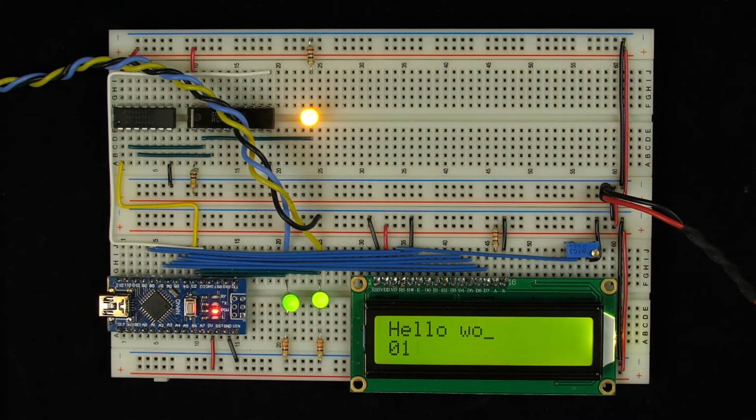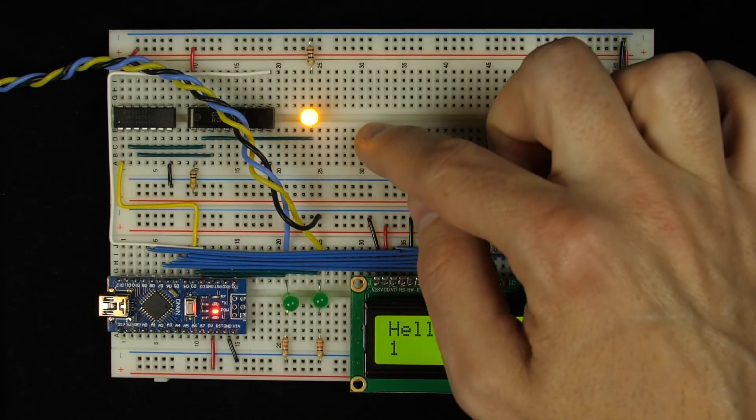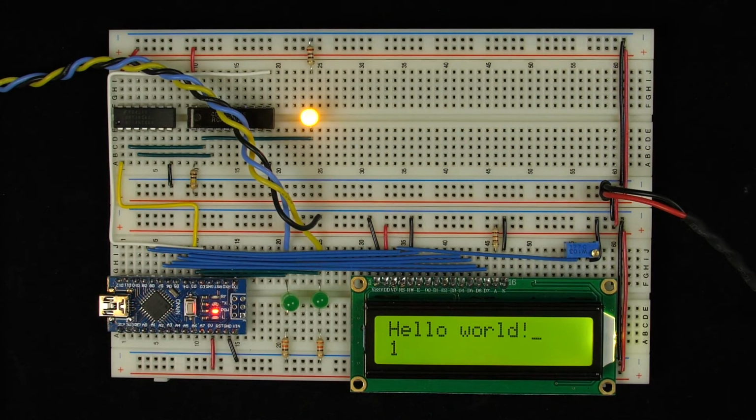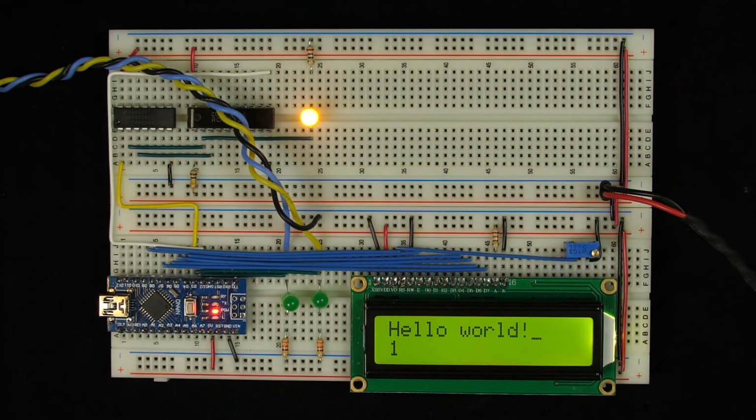So let's take a look at the receiver again as we receive a message. Now again, we've got this message where we received hello world without a comma. So was that a mistake or not? Well, because this LED is on, we know we received an odd number of 1s. But now we also know that our transmitter has even parity. So counting the parity bit, the transmitter will always transmit an even number of 1s. And so anytime we receive an odd number of 1s like this, and this LED is on after we're receiving, we know that there must have been an error. Because the only way we could possibly receive an odd number of 1s is if some bit got changed along the way after it left the transmitter. Either a bit in our message or the parity bit itself.